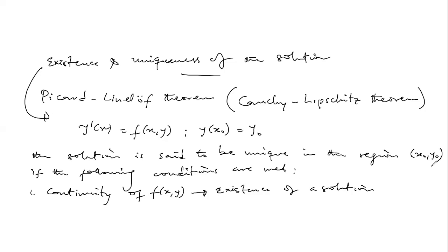Now recall your stability, where you say BIBO stable. It means that a bounded input must give a bounded output. So the amplitude value of your input must be finite, and then the output also must be finite. But if at the end of the day the output is infinite, then it is not stable, and we will say that there is no unique solution because it is diverging instead of converging. Does that make sense? So now, once we are able to confirm continuity based on the fact that there's a polynomial of that expression, the next thing to do is to confirm uniqueness, a unique solution.